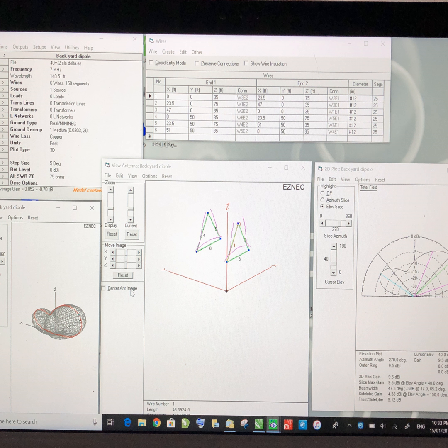And then it's a question of getting the antenna up into the air. So you may be supporting it from a tree, a mast, or part of the house. The important thing is to keep it in the clear, keep it away from other objects if you can, and get it as high as possible. Once you've done all that, you will want to test it out, obviously. You might just connect it to your radio.